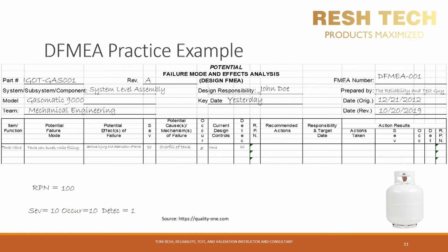This is why prioritizing actions to work on first and determining test sample sizes for your validation and reliability tests based on RPN values is fallacious and potentially dangerous, as you may miss critical failure modes with a high frequency of occurrence, since RPN does not discern or weight severity, occurrence, and detection independently. This can be dangerous if you set a minimum threshold for high, medium, or low priorities for each failure mode using the RPN, as you could end up overlooking or waiting until late in the design game to verify and validate a potentially catastrophic failure mode.